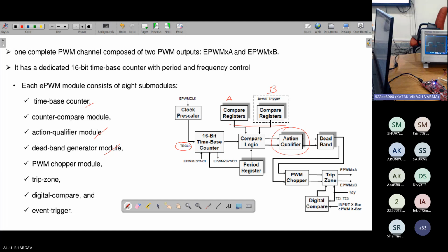in the inverter. In an H-bridge inverter, one leg consists of two switches, and there will be deadband between the two complementary pulses, because in a practical scenario the pulse generation output of the driver and the switch will have some delay to turn on and turn off.